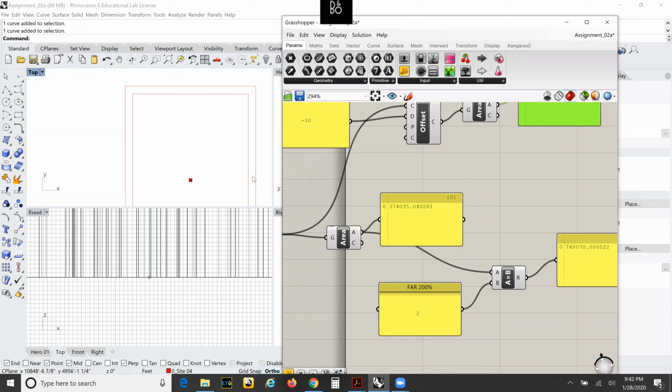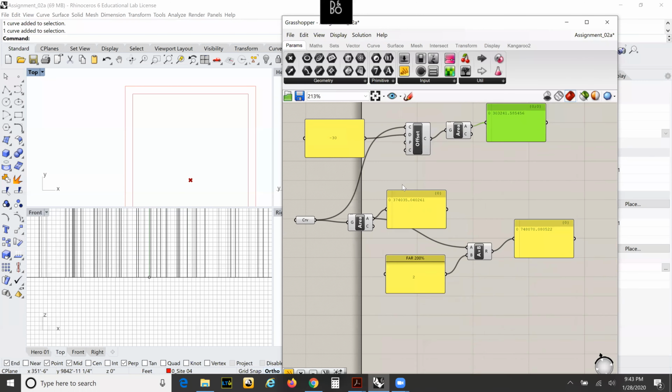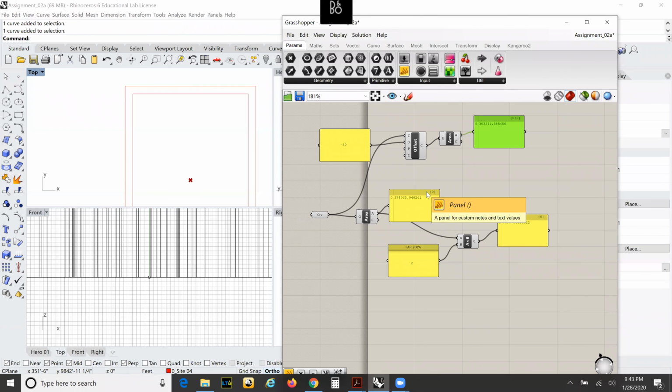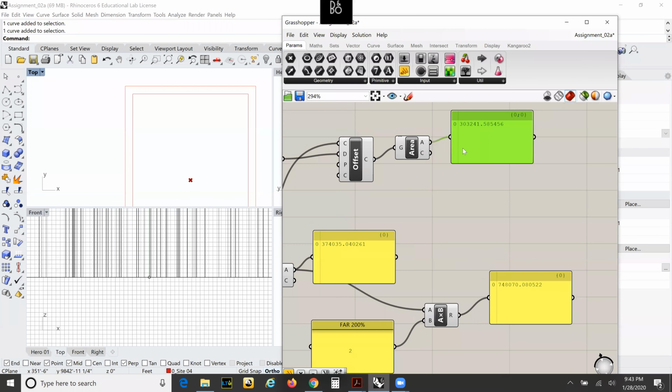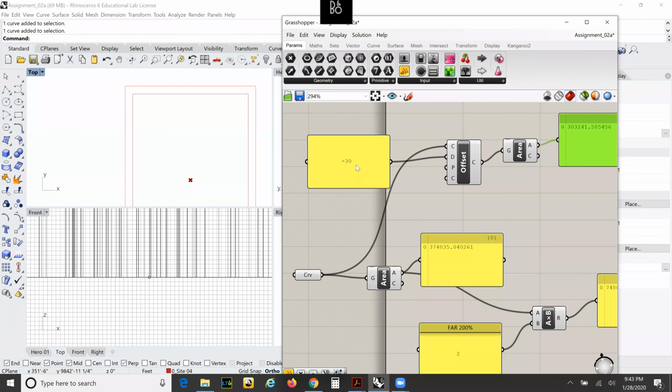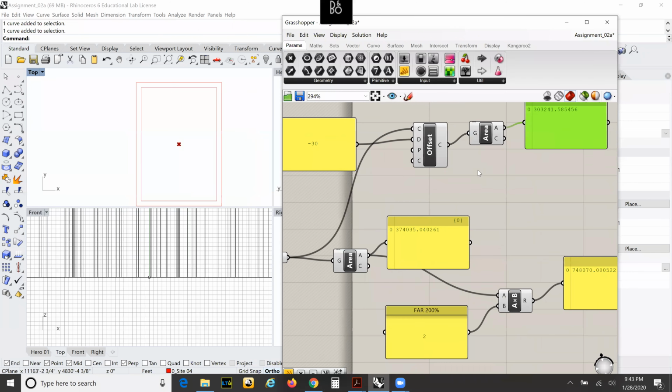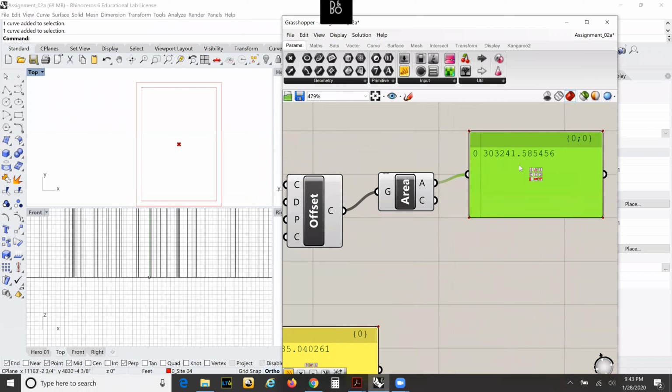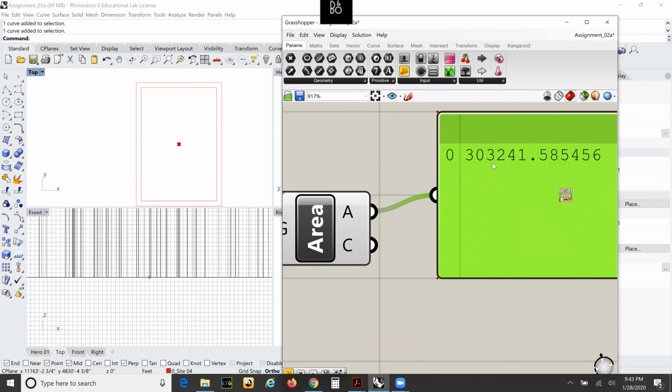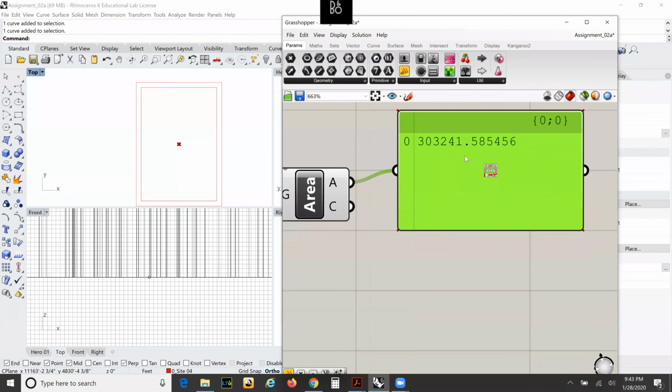When you're in a neighborhood, there's always like a 15-foot or a 5-foot setback between each house. You can't build right next to the house next to you. You have to give it a setback. All that's controlled through the city. So in this case, we have a 30 foot setback all around the perimeter. So technically our buildable square footage is 303,000 square foot.